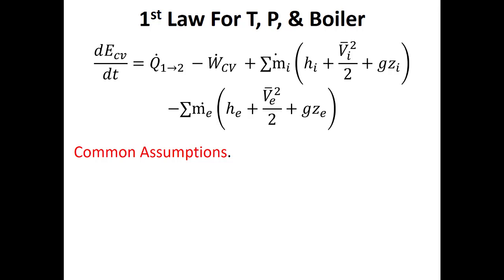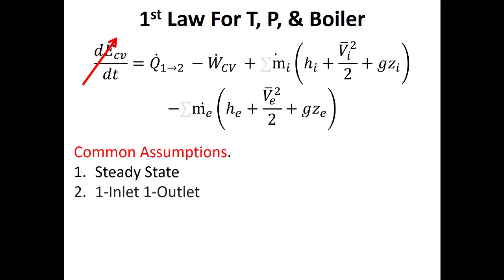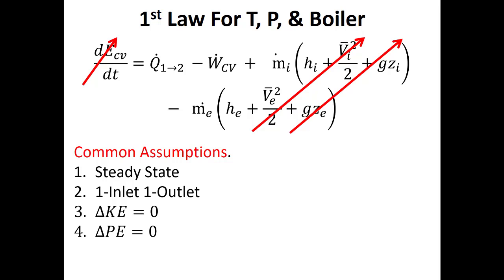So the textbook will just give you equations, but I'm always in favor of deriving those equations ourselves from the first law, because then on a test, like the one you're going to write tomorrow, you'll demonstrate to me that you know how to make the different assumptions that simplify this long version of the first law we have for open systems. You're going to simplify that down into an equation that we're maybe more familiar with for heat rate or for power. So you'll assume things like the systems are at steady state. There'll often only be one inlet and one outlet. We'll often assume that kinetic energy can be neglected and that potential energy can be neglected.